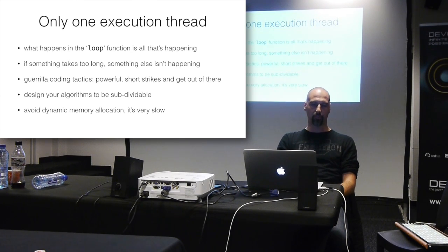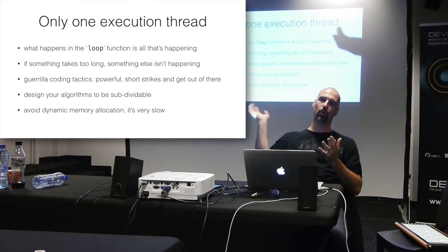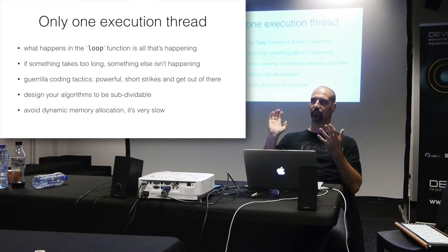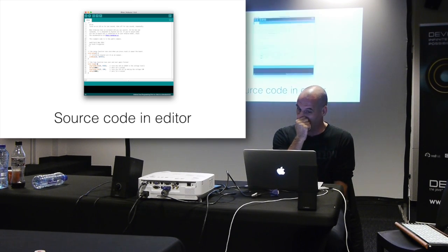And then one very important part there is, if you're used to relying on the garbage collection, don't, because you cannot have any garbage. If you have dynamic memory allocation in such an embedded device, it will really grind everything to a halt. So you start thinking in fixed data structures, and you start thinking in how data organization and the algorithms about how you organize the data are going to solve your problems, and not like, let's throw 1 million objects at the problem and it will solve itself. You can't, right?